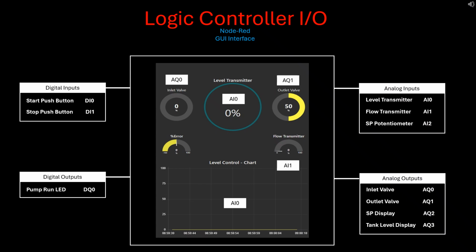The difference between the PV and SP is termed the error, expressed as a percentage. Response is charted to monitor and tune the system over time via the PID settings, which are used to achieve the optimum response curve, known as quarter wave tuning.